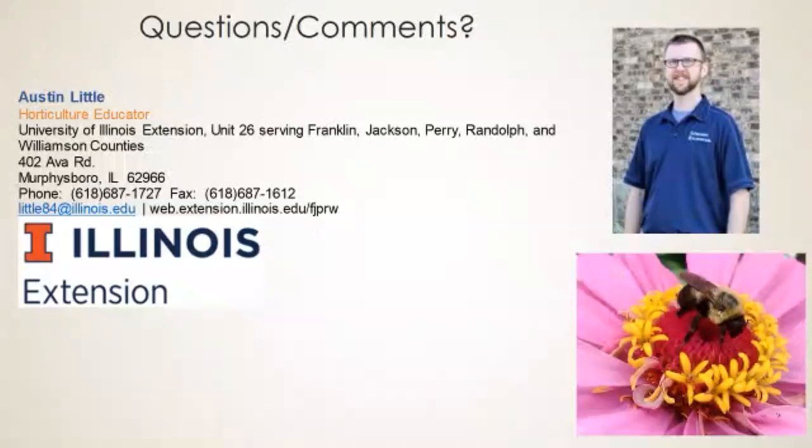But then we have bearded foxglove and other things like that. So they adapt. They can adapt. It's just that primarily, the most common green roof cover for extensive green roofs is sedum, or Sedum kamtschaticum, or some type of mix of sedum species. And there's a few native sedums, but most of them are non-native.